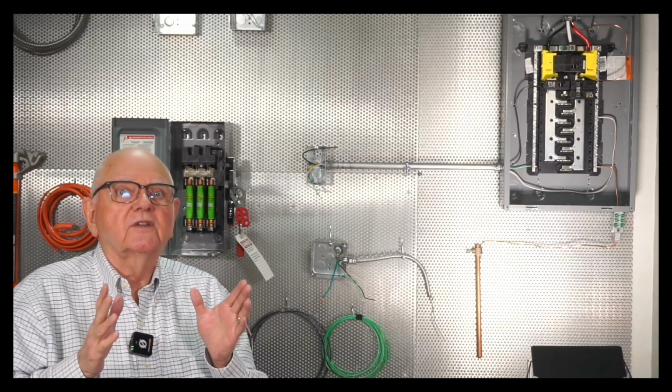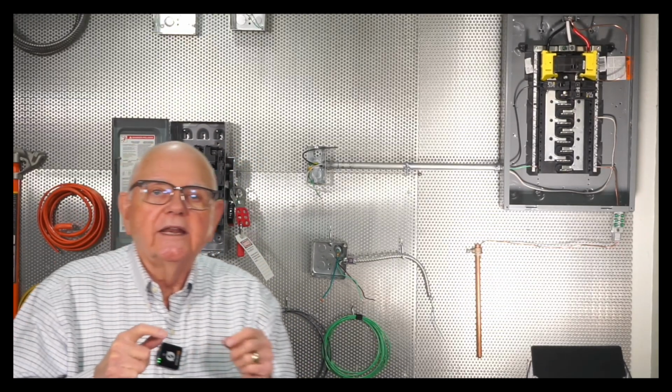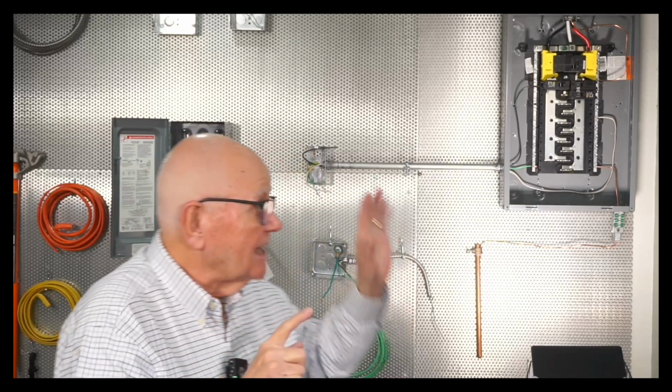Now, I can also have an individual branch circuit, defined in Article 100. An individual branch circuit just simply means that I only supply one piece of utilization equipment with that particular branch circuit. I can also have an appliance branch circuit where I have one or more appliances attached to my branch circuit, but I don't have any luminaires attached to it. And then I have the multiwire branch circuit.